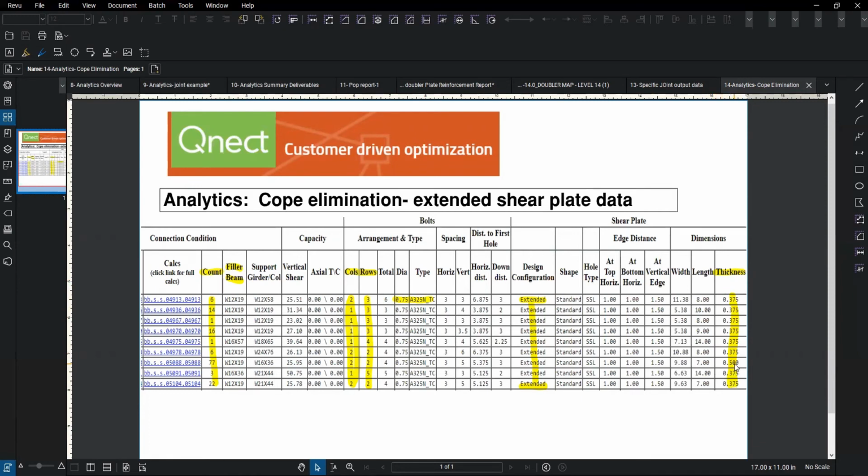Any cases where it's 1/2 inch shear plates and under a single pass weld, this is a great option. We had a job with 6,500 of these, 6,000 were 1/2 inch and under, so we did those as an extended. 500 went from 3/4 to 5/8 to 1 3/4 inches, so we did those as standard shear plates, maximized the return for this client accordingly.